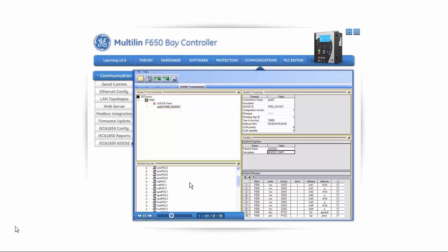In the Dataset Sources window, expand the F650 data source icon, and then expand PHTOC1, which stands for Phase Timed Overcurrent. In situations of heavy load, the phase timed overcurrent can indicate an alarm or even generate a trip if the overload is too much for the primary equipment to handle. Here, we will send the PHTOC1 operate flex operands and consider them as alarms. Similar to what we did for the reports in the previous section, drag and drop the OP elements: General, Phase A, Phase B, and Phase C. Remember to drag from the GOOSE dataset sources and drop into the dataset elements.